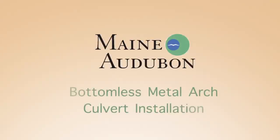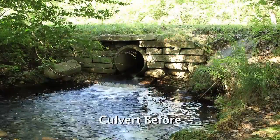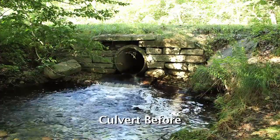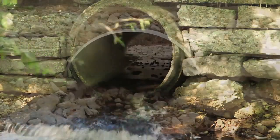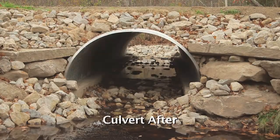Bottomless Metal Arch culvert installation. The existing culvert was what we call a hanging culvert. It was perched up above the channel bottom. The outlet basically was too high, so the water dumped down into the brook, and it was too high, didn't allow fish passage. We thought this would be a good opportunity since the arch seemed to fit really well, and it was an economical solution as well.